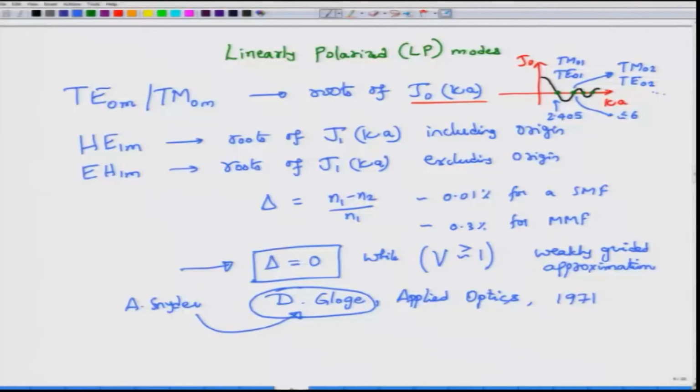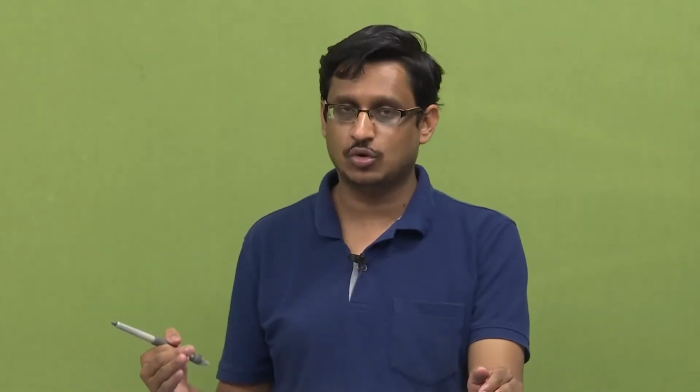or it can be a curse. Most of the times it is a curse, but with sophisticated signal processing algorithms, these different modes are now being used to increase the capacity of the optical network in something called mode division multiplexing. Anyway, these are topics that we are going to discuss later during the course. So, it is good in some sense to work with many modes, but that many mode propagation is not for long distances. For long distances, you are mostly looking at a single mode operation.